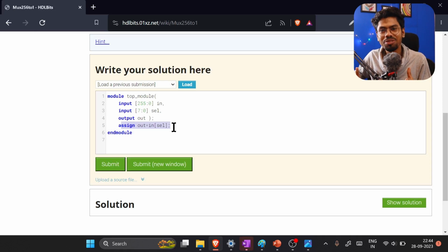So if you want to write the description at the gate level, it will take at least half an hour to 45 minutes. But with the behavioral domain, we can write it in one line and just try it out to see if it is working or not. If it is working, then we have the facility inside the commercial Verilog tools, where it can generate the netlist or the gate-level Verilog code from here.